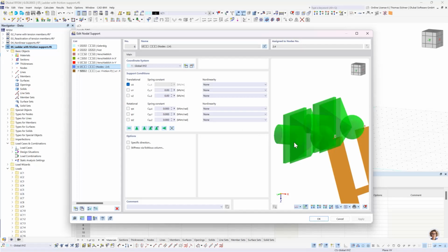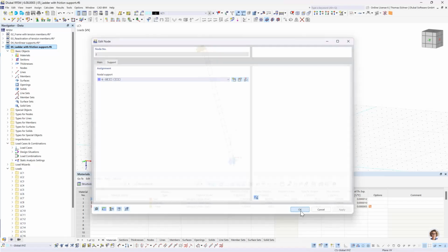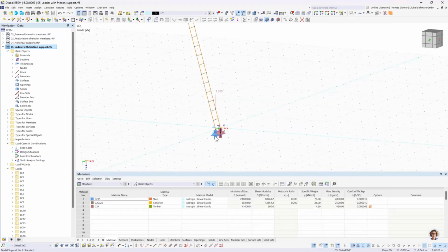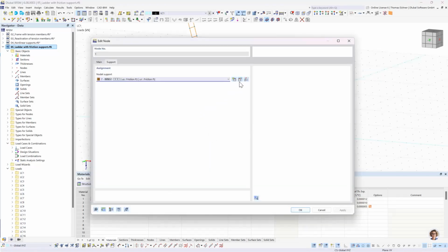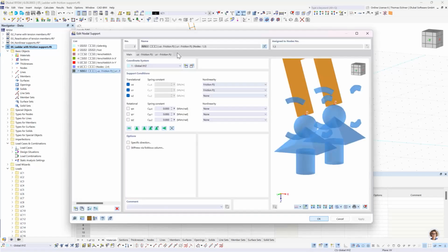On the bottom, it stands on the ground, so it is supported in z direction. We could also implement a failure if negative, but that's not needed right now since we only have vertical forces from the top to the bottom, so it's gonna hold anyway.